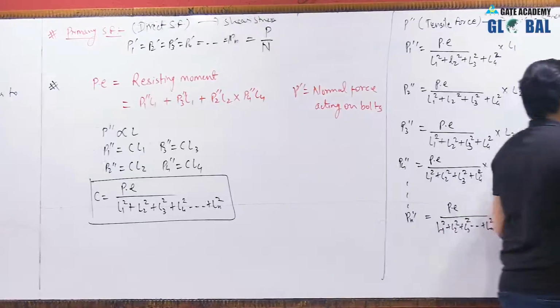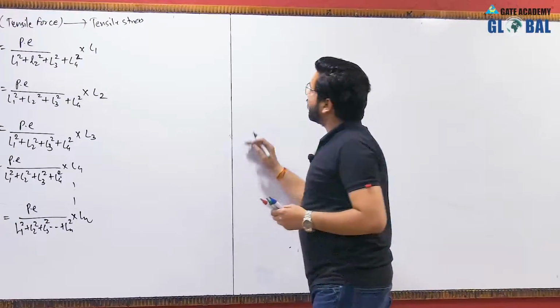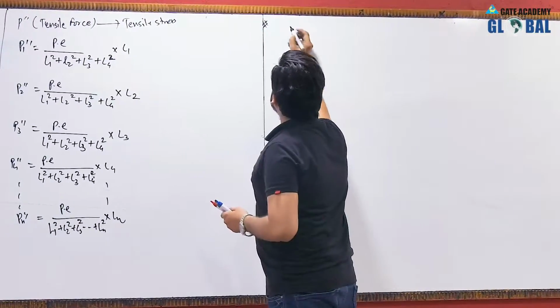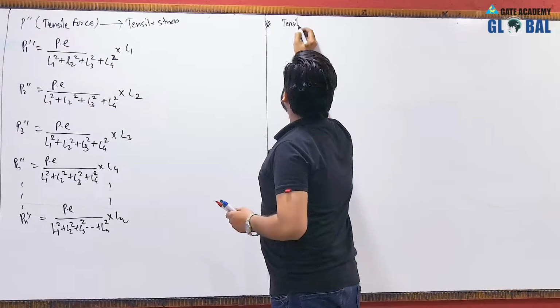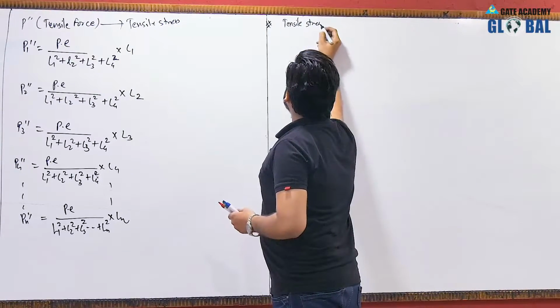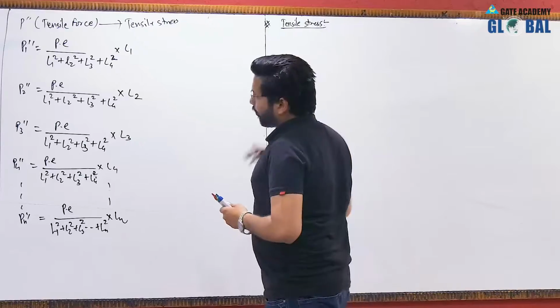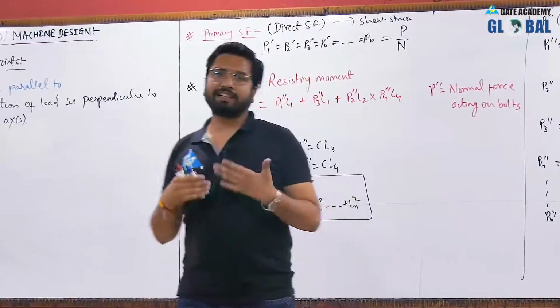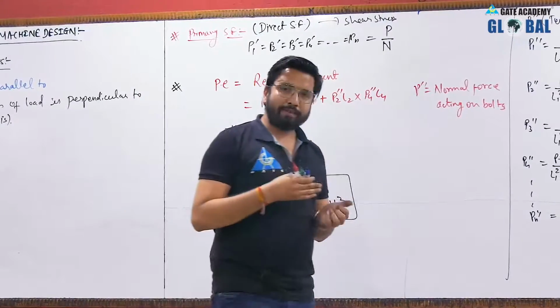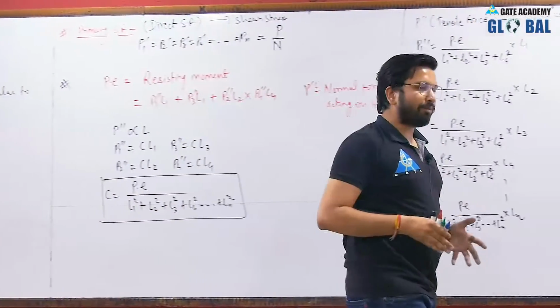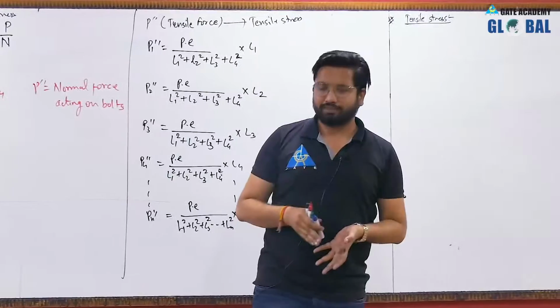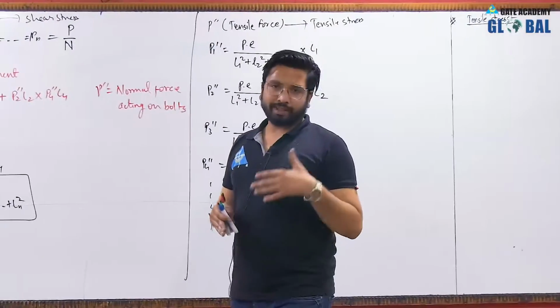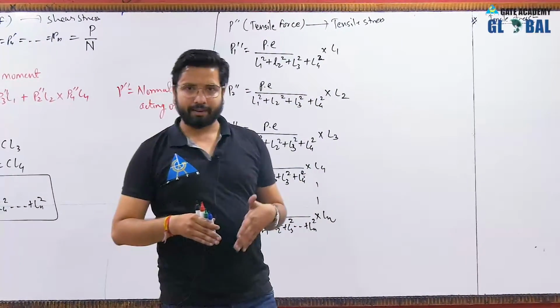Now the tensile stress on the bolt. Here comes the problem, as I have told you earlier, that in tensile loading we may consider the core diameter. So when a bolt is subjected to a direct tensile force, in that case we will majorly consider the core diameter.